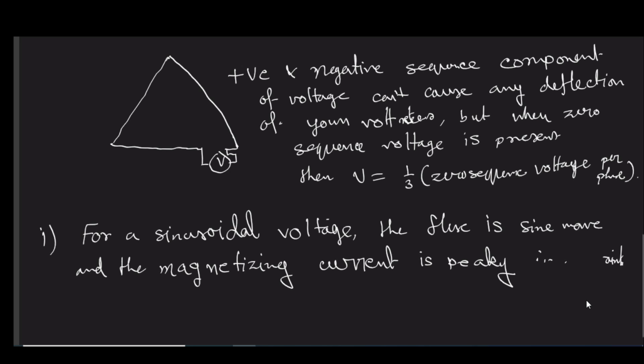So here I am not writing it because I cannot write it for a single phase one. This positive, negative, and all these are applicable to three phase in the context of three phase analysis. It is meaningless to describe this in the context of single phase, but you can understand when you connect all the three transformers, if you form a transformer bank, the individual transformers preserve their individual characteristics. There is no such huge change in the individual transformer characteristics, right?